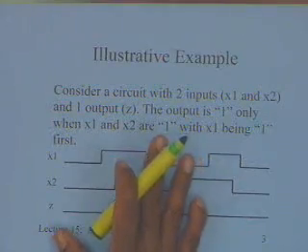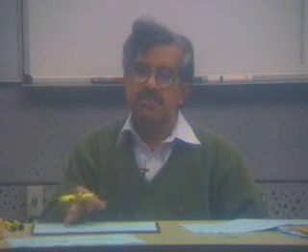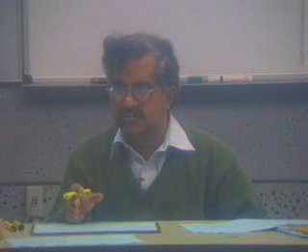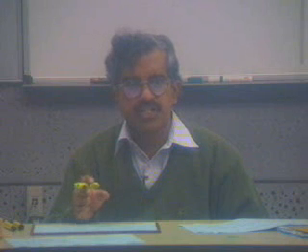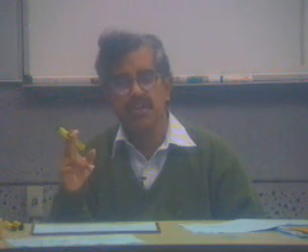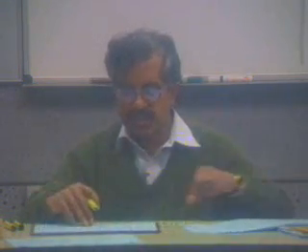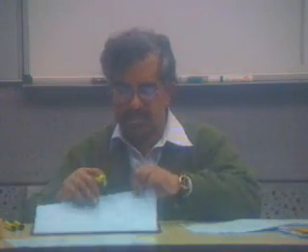See, all these things that we are doing over here, you can also do through a sequential machine, except that you will be doing a synchronization with the clock. That is, when you start implementing a synchronous sequential machine, input changes within the clock are not important. Within a clock, let us say an input changes twice, you are still going to make only a transition corresponding to the last input change. Let me illustrate this point because this question has come up.